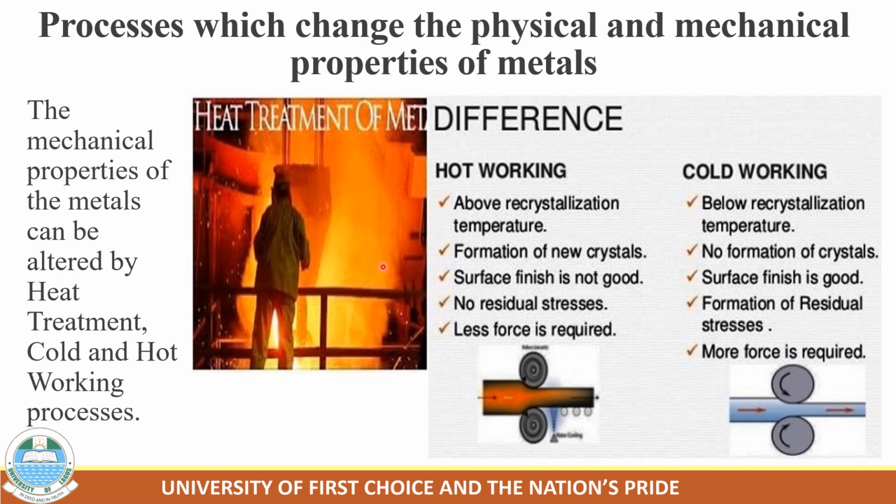When it is heated to Austenite temperature, it gives the microstructure of that material free movement to move from one place to another. They will easily move around. So when the material is heated to Austenite temperature, you now quench it. You insert that material into a quencher. Maybe you quench it with water, brine solution, or oil. Quenching your material with water or oil will drastically restrict the movement of the microstructure inside the material and make the material hardened. It will make the material seriously hardened.